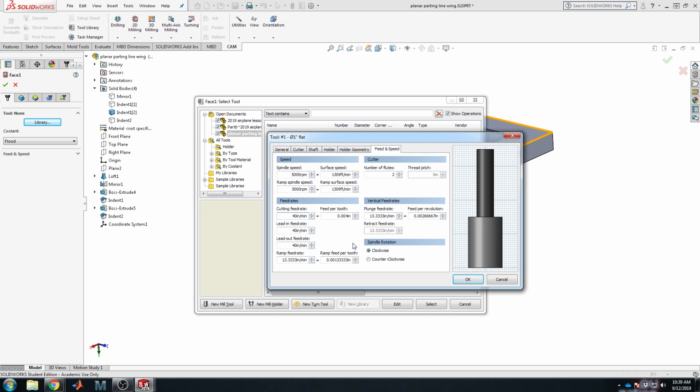That's probably plenty fast enough. For various reasons we can discuss, mainly being the inertia of the machine, the strength of the stepper motors involved, the horsepower of the spindle, on and on and on, 40 to 50 inches per minute is fine. Some high-end machines in industry can be over 1,000 inches per minute, and sometimes over 100 through hard metals like aluminum. 1,000 would be probably in some very light material like foam.